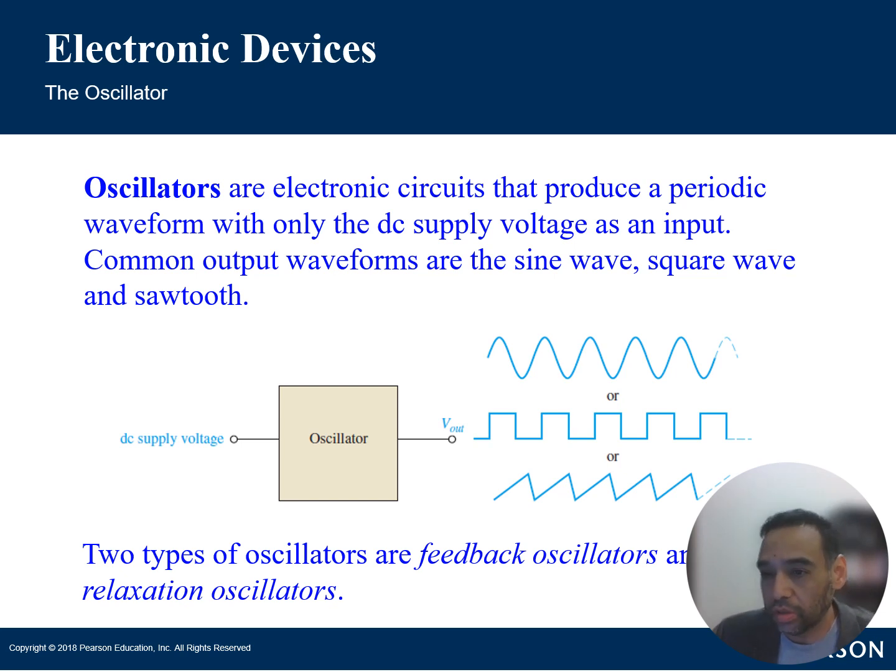But yeah, the very first time you initiate a circuit for an oscillator, you may have some oscillation or you may not, and there's going to be some trigger that actually gets it started. We have some kind of nonlinear element. So oscillator circuits typically include nonlinear elements. I've been talking so far about linear elements over and over again because we like to design in the linear region so we can be stable and predictable, and most of all we want to be stable and predictable because we want to design something that's safe for the public, right?